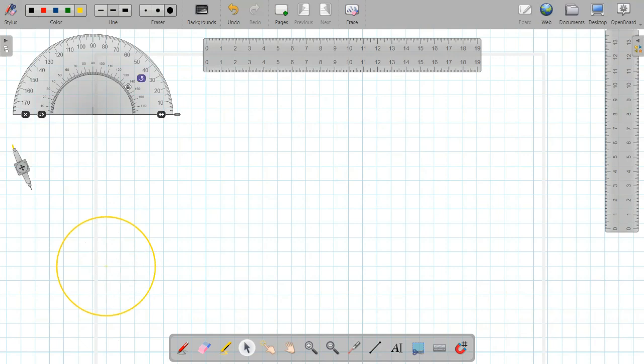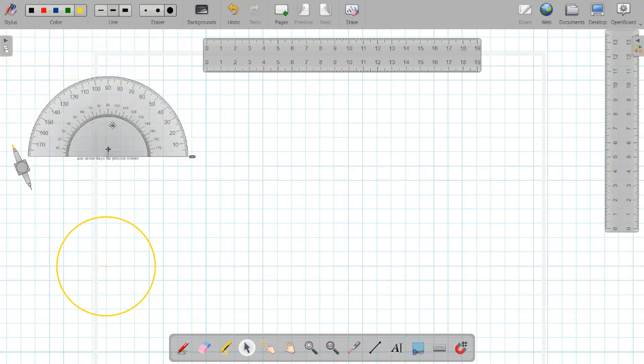Now, after doing this, we have to divide the circle into equal parts. Now, equal parts can be 8, it can be 12, it can be 16, it can be 4, anything. But as we increase the number of parts, the construction also increases. On the other hand, if we decrease the parts, we will not get the actual or smooth curve. So just to maintain the balance between the construction part and the smoothness of the curve, let us stick to around 8 parts, or dividing the circle into 8 parts.